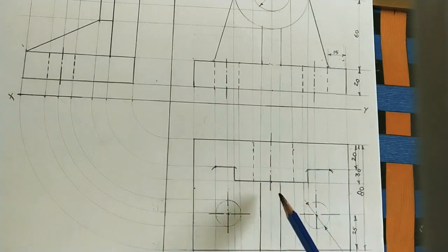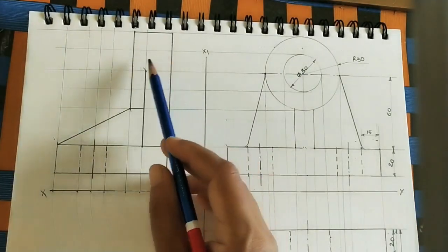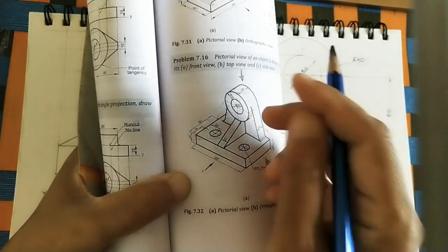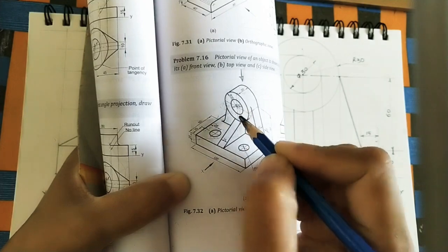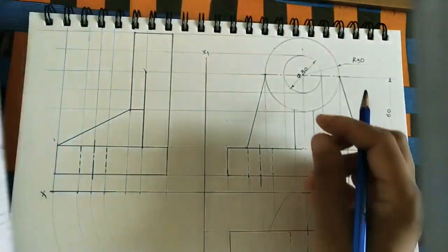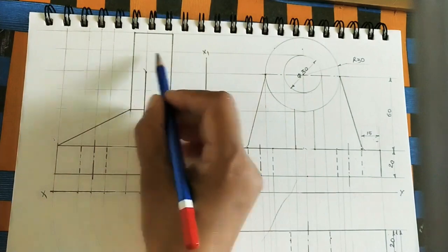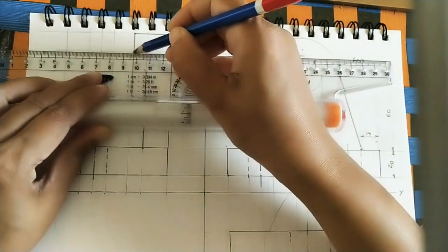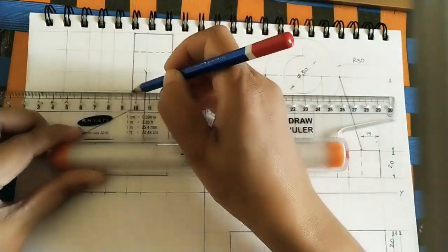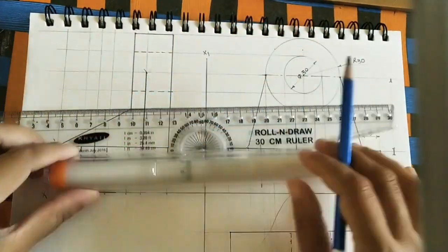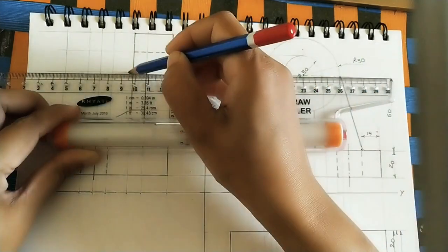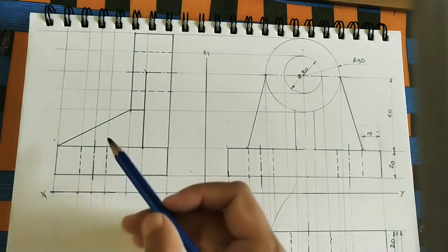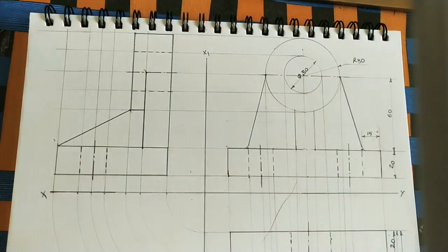Having got the circular hole in the top view, we need to take the circular hole in the side view also. Okay, from the side we can see this bigger corner and this thickness, and we can't see this circular hole inside this. So whatever projectile lines are coming, those should be dotted, because it is the invisible part, so make dotted lines. Now at the center do the axis line. Now this is a complete side view. Here already at the center of the circular hole we did the axis line.